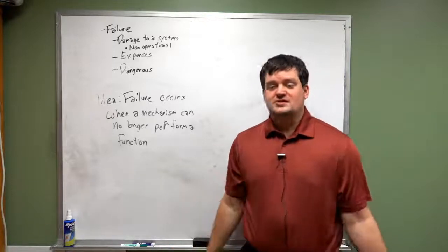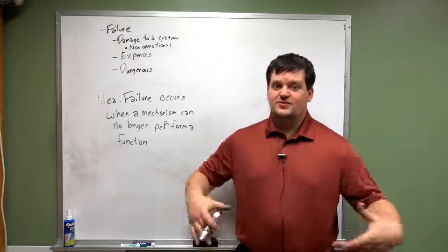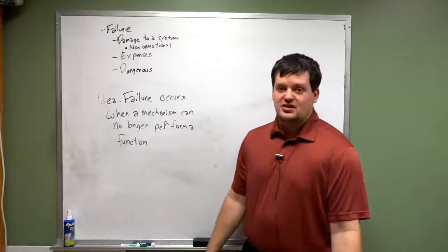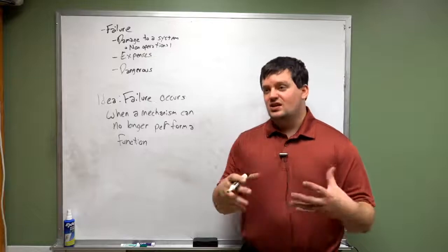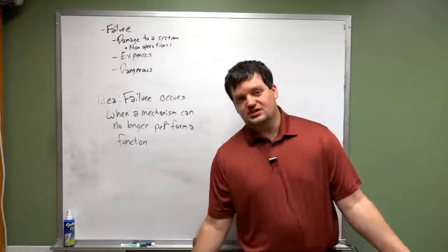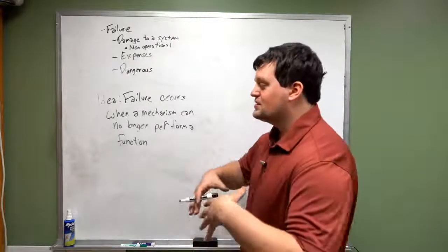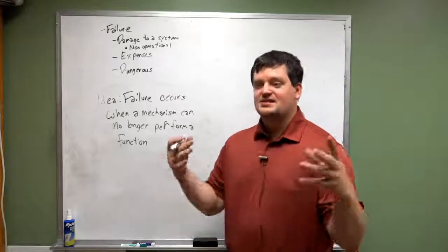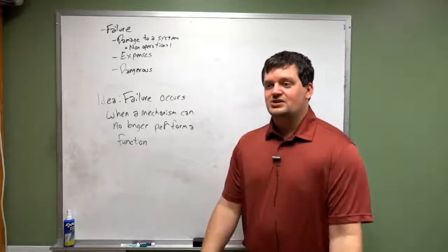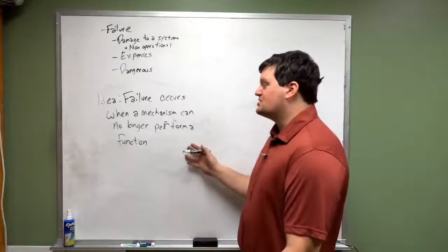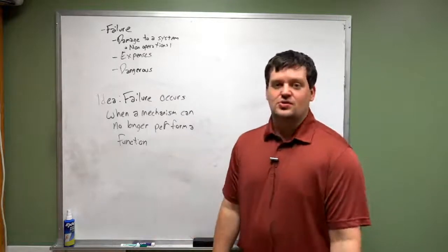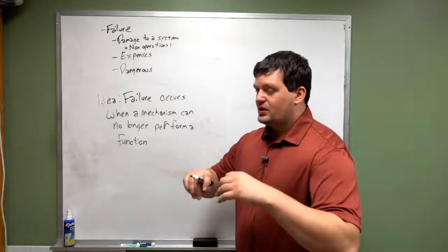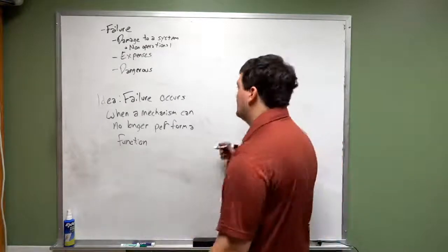And all of those reasons you can try to prevent for. You can design it so that no sand gets into your gears. You can design it so that all of your bearings are shielded. You can pick all of these components and design shielding and design casings and really try to make sure that all of these tertiary failure mechanisms don't happen. But on a component level,